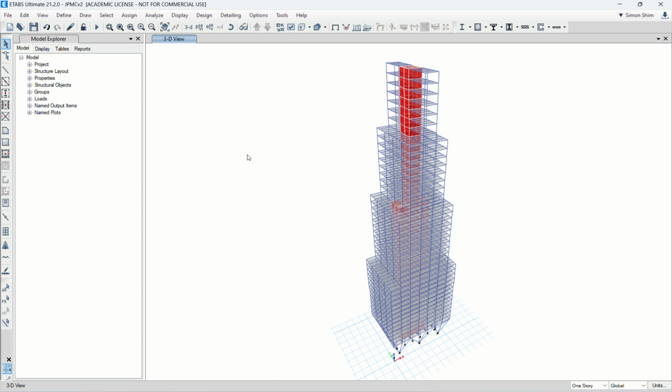so that design pressure times tributary area, which is width times floor height, right? For wind load calculation and also from the structural 3D analysis standpoint, we treat each floor, made out of metal deck and concrete slab, as relatively infinitely stiff. So this is our slab, right?